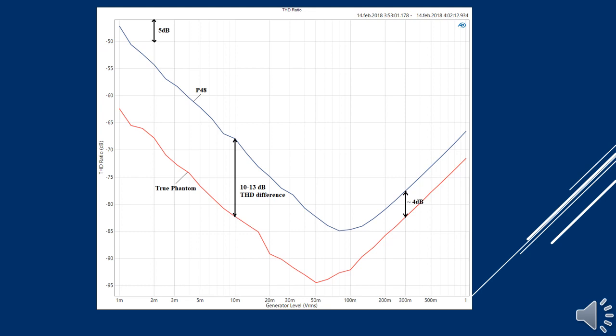So this is the difference in harmonic distortion, just focusing on the harmonic characteristics. And I'll show some FFT plots in a moment. Sooner than that, what we have in here is I just put in, with the AP analyzer, a signal from 1 millivolt out to 1 volt, and we're seeing the differences in the THD over this particular input range.